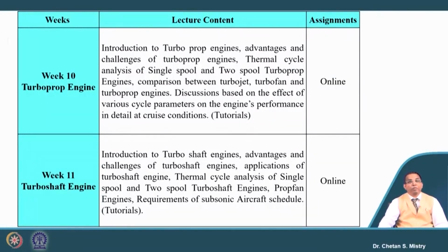Then we discussed the turboprop engine, where the whole thrust focus is based on the propeller. So basically the propeller was generating the thrust, and we have seen research and ongoing applications showing thrust generated by the propeller as well as by the exhaust of the gas turbine engine. So we had two thrusts coming: one because of the propeller, and the second because of the exhaust from the nozzle.